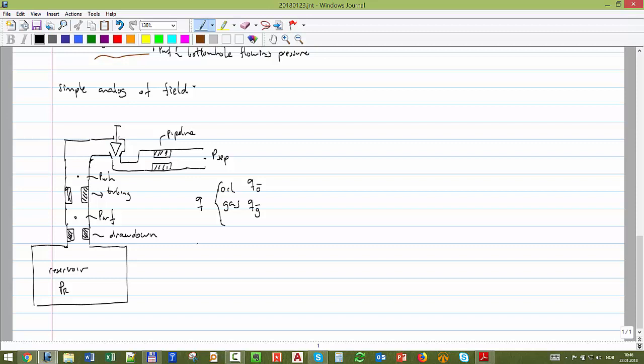So I'm going to ask you, this rate that I have, it depends on what? Pressure drop. Choke opening, but let's just wait. In first principle, it is proportional to the difference between PR and P separator. That's the driving force behind the rate. And now I can change that. So what's going to happen with the separator pressure with time? Constant. Why?